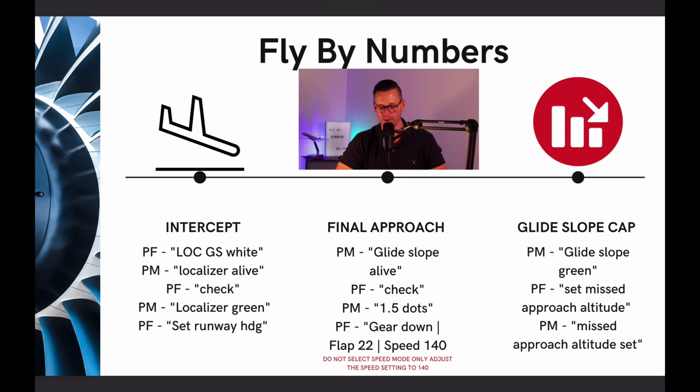The response from the pilot flying, gear down, flap 22, speed 140. And we do that as one call. We don't wait for the pilot monitoring to do each of those things individually. We call it as one call. Gear down, flap 22, speed 140.